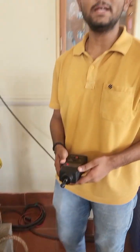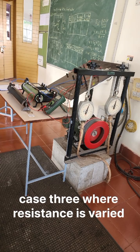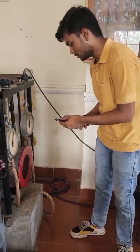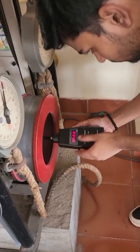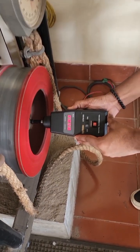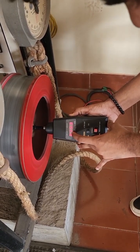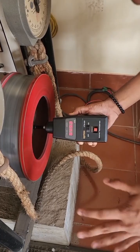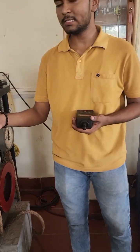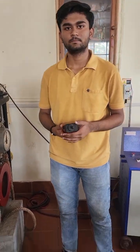So yeah, the speed is increased. So let us see whether the speed has been affected or not. The earlier speed was around 450. Now it is showing 509, which is around 500. So we can consider it as 500. So yeah, with increasing resistance, the rotation per minute of this motor has increased.